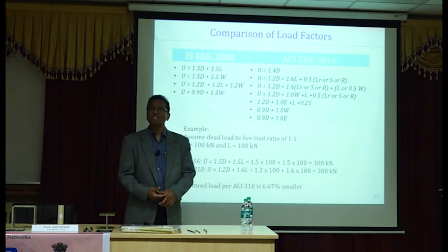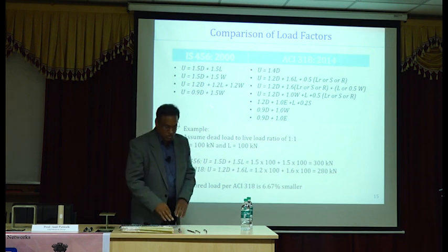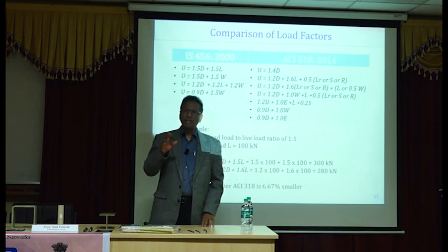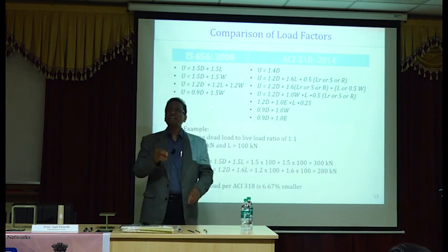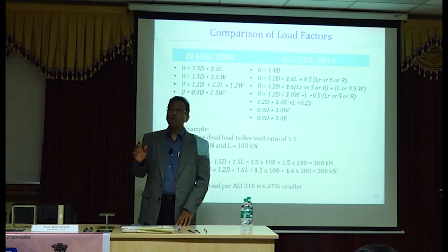There are two things. One is it gives you warning. If you have very large deflections, you know that something is going on, so you run. That's number one. Number two, ductility provides the ability to maintain the load carrying capacity under large deflections. That's the pure meaning of ductility. Ductility of a structure is the ability of the structure to maintain the load carrying capacity under very large deflections. So the whole purpose is that there is no collapse.